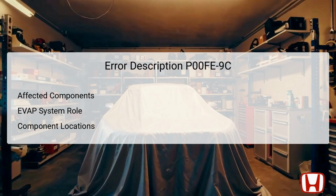The components affected by the P00FE-9C code include the fuel tank system, the EVAP canister, and the Enhanced Leak Check Module, ELCM. The fuel tank system is responsible for storing gasoline and vapor containment. The EVAP canister functions to capture fuel vapors before they escape into the atmosphere. The ELCM continuously monitors the pressure and integrity of the EVAP system.